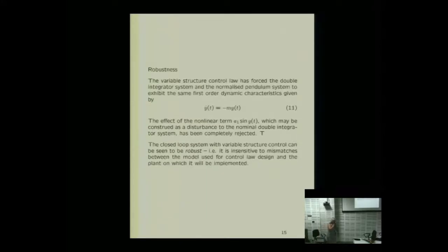So, how does it do it? It's really quite straightforward in terms of a paradigm. We've just taken a system, we've defined a dynamics, we've made sure the control is big enough to ensure S and S dot have opposite signs. And clearly in the calculation we did for the double integrator without uncertainty, the size of the disturbance will come in. So we can already picture in our minds from the structure of the mathematics, definitely from what we've seen this morning, but maybe using the knowledge we brought to the course anyway, that the size of the control is also going to have to be modulated by the norm of that uncertainty, because we need to still ensure that S S dot has opposite sign, and that S S dot equation will be determined and affected by the uncertainty.